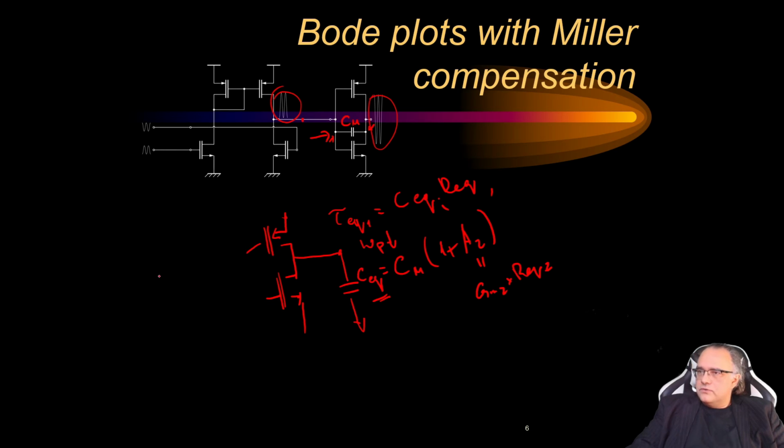Alright, very well. So this means that for the phase rotation, the first pole is already at a very low frequency, and then the phase becomes rotating here, then it completes its rotation of minus 90 degrees, and the gain actually starts reducing at a much earlier frequency.